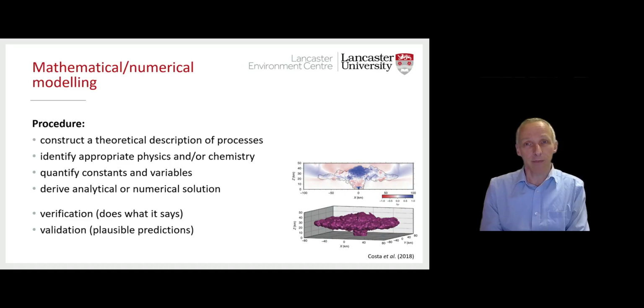The output is only ever as good as our understanding of the underlying processes and the quality of any values that are input into the model. Thus, model output should always be considered with appropriate caution. Initial simulations should be verified to ensure that the model is working internally as expected. So, for example, to ensure that errors haven't been accidentally introduced when writing the computer code. So, wherever possible, the model results should also be validated by comparing with known observations. For example, with field-based measurements of past events.